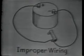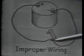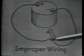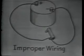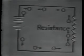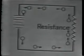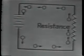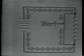Also, improper wiring could cause a short. Here, both leads of the battery are connected to the same terminal of a resistor. This amounts to connecting the leads together and again could damage the battery. So, a power source needs some resistance in the circuit. This resistance will regulate the current and keep it down to a normal value. Shorting across the resistor will eliminate its effect and there will be no regulation. This will allow a very large current to flow in the circuit.